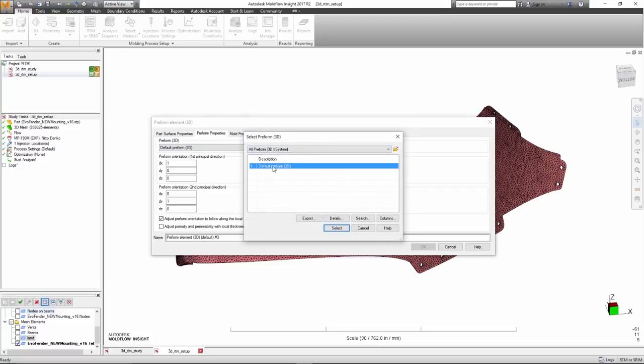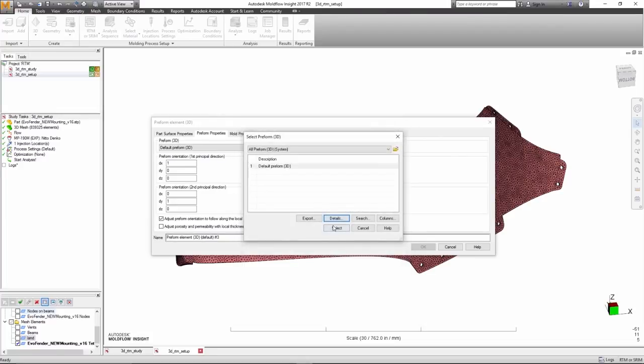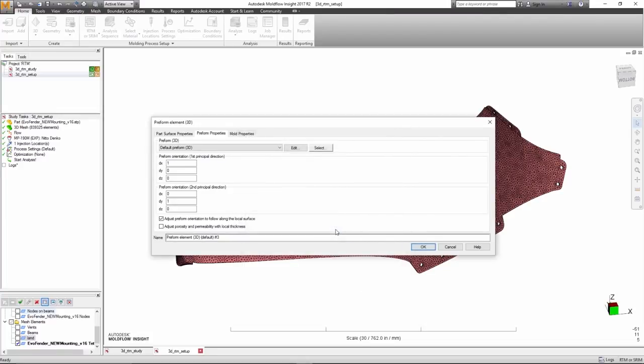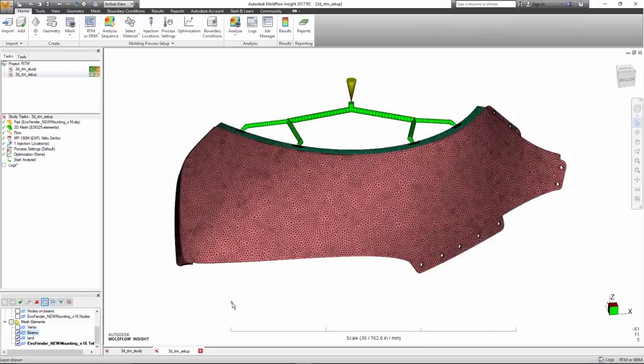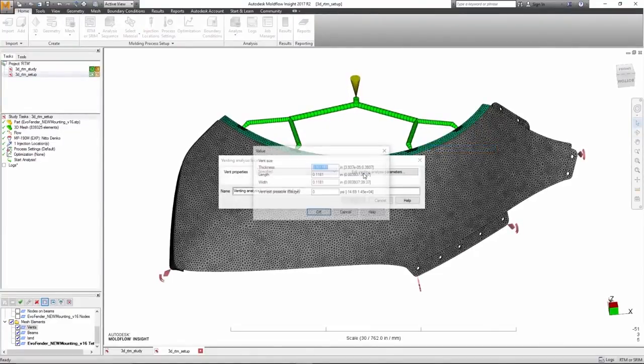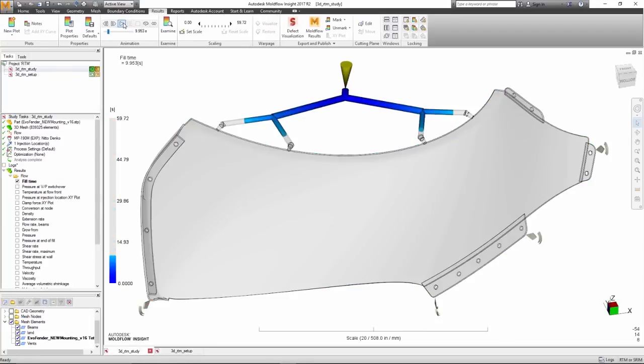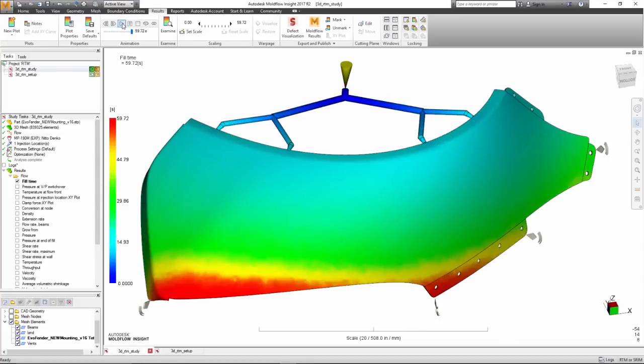In the Moldflow 2017 R2 release, the end customer can provide a preform 3D property to the area that the preform will be placed. The user can then specify the permeability properties for the preform and the orientation of this preform in the mold. The software will automatically have the fabric follow the contours of the part. The simulation can be used in combination with vacuum locations to promote permeation of the fabric. The analysis also predicts the filling pattern and identifies problems such as cycle time.